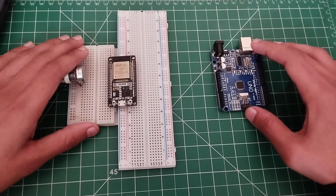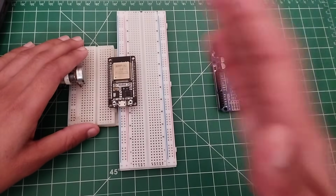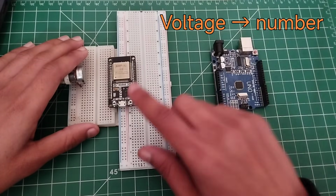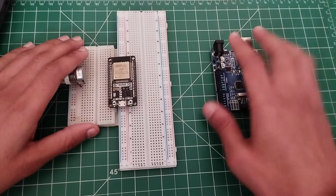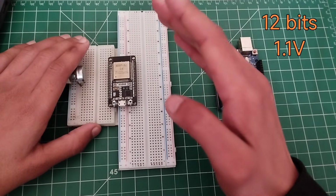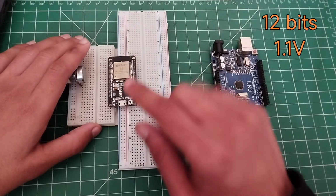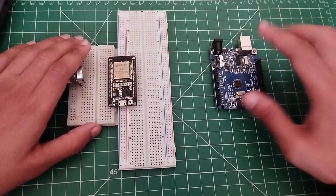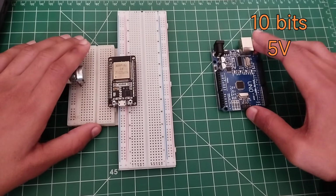Now before moving further we need to understand ADC. So ADC converts a voltage, which is nothing but an analog signal, into a number, and ESP32 ADC is different from that of Arduino. The ADC in ESP is of 12 bits and its resolution is 1.1 volt, which is the hardware limitation of this ESP. But if we talk about the Arduino, its ADC is of 10 bits and the resolution is 5 volt.